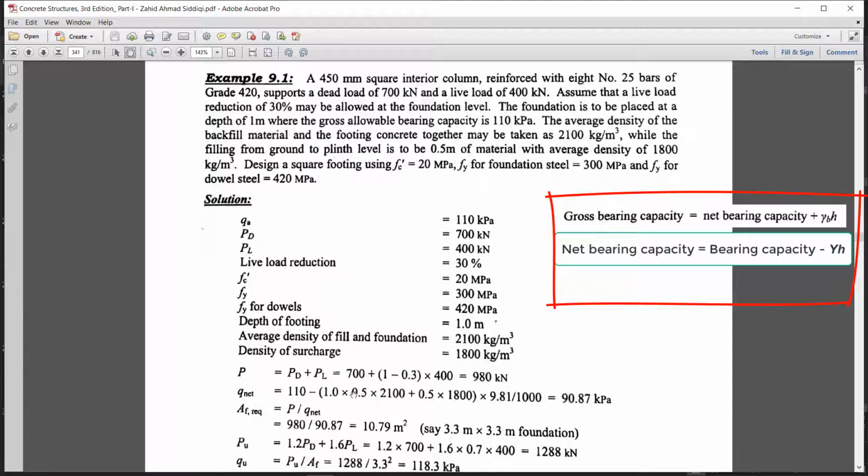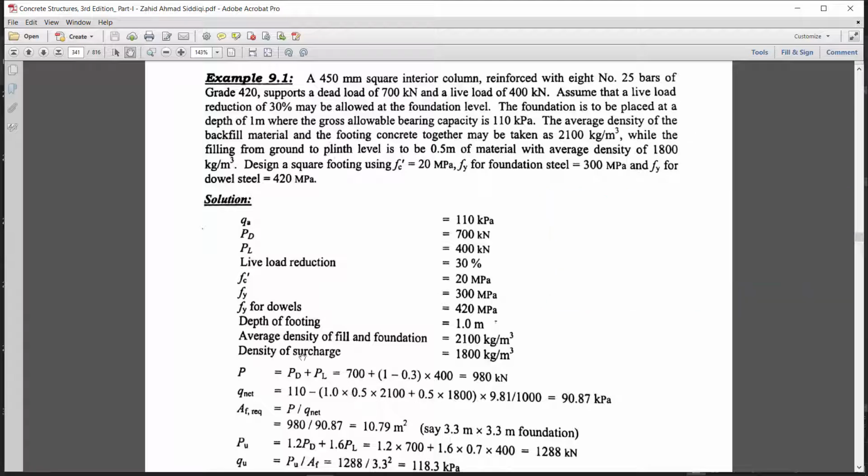So the backfill load, that statement is given in the previous pages, that whenever you consider the backfill load, then you have to use the factor of 0.5. So you have to not consider the full, because that is a backfill load, and second the weight of the footing will be again included in the design of the footing. So you no need to calculate the full load. So you have to consider half for the backfill load.